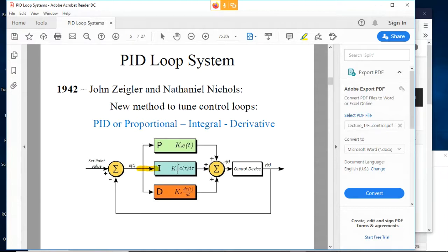So what we can do is add integral control. Basically, integral control integrates the error. So it keeps adding the error: if there's any error, we add and add and add, so the integral keeps going up and up and up. It's accumulating this error. As you go through the control loop the first time, you may have a little bit of error, maybe you have a whole bunch.